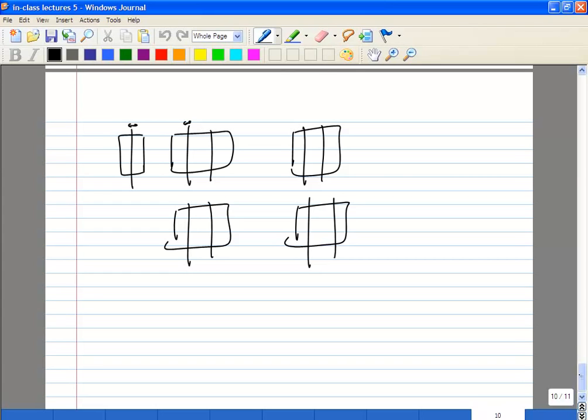So normally, the gate shadowing effect is one effect which we talked about. There are actually a couple of other effects which also go on. So typically you want that to be identical to your main transistor. We'll look at one of those effects today, where it doesn't directly depend on the length, but on the region of active around the transistors.